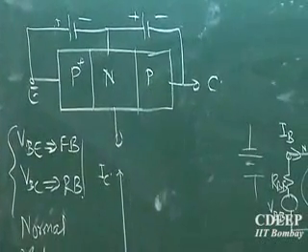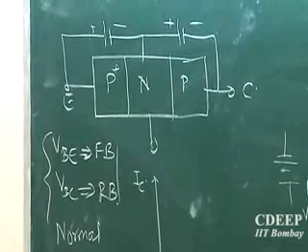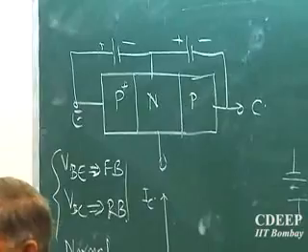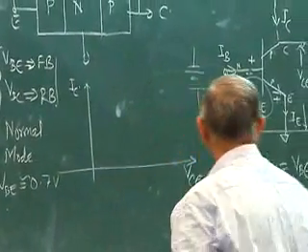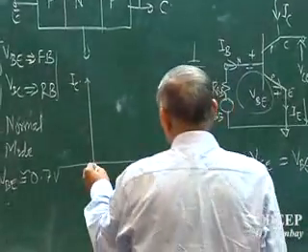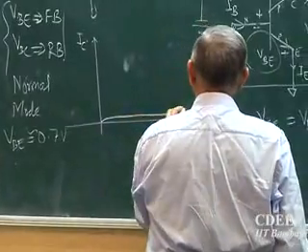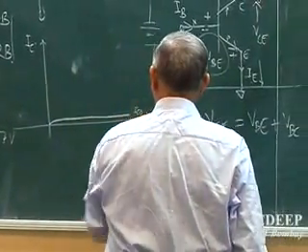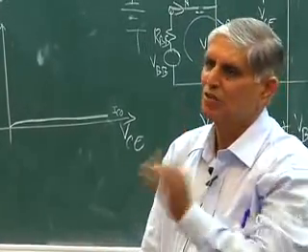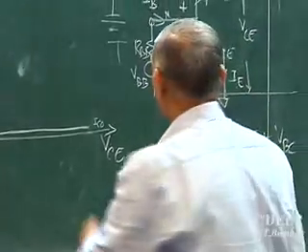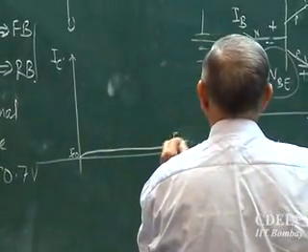And therefore there is no collector current, because there are no carriers coming from the emitter which can reach, except the reverse saturation current, which can flow. Even at zero bias, reverse saturation current can flow. So if I see the characteristics, even at IB, maybe very small current, which I will explain later, is called the collector saturation or open circuit collector. We'll define this later. This is ICO.